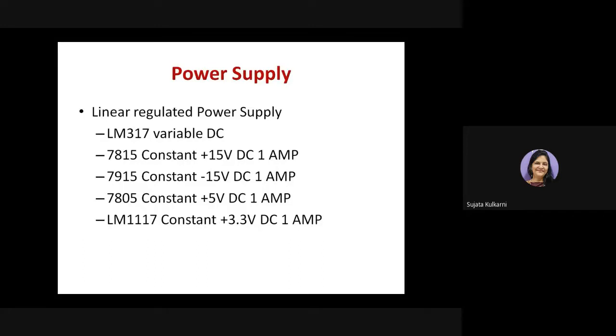So for this entire board, all the experiments, when you are interfacing devices like DC motors or stepper motors, you have to keep it in mind. These are the limitations. In any electronic system, load means current. So you should never ever exceed the specified amount of current. Otherwise, you are going to damage not only the drivers, but also the power supply. So you must always work in the given conditions. You are working in a constrained environment.